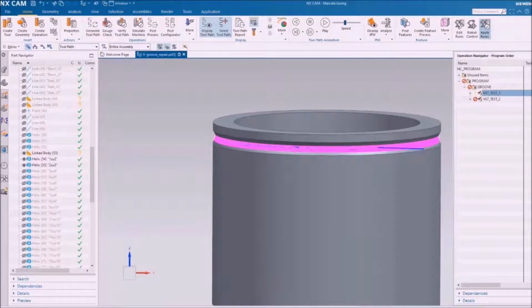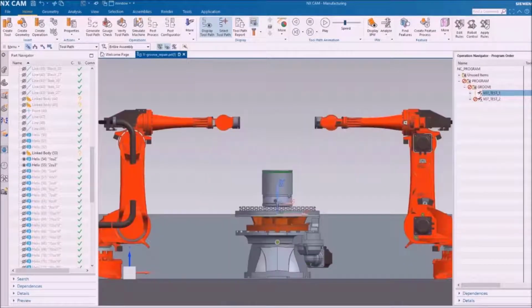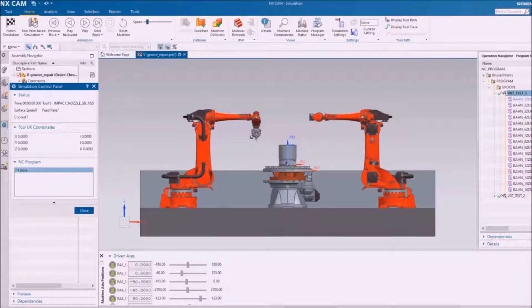A spiral path that repeatedly crosses the center of the groove and is extended outwards by 1 winding distance before each turning point. Since all tool speeds and orientations with respect to the workpiece surface and all applicable robot rules are already set, the simulation can be started now.